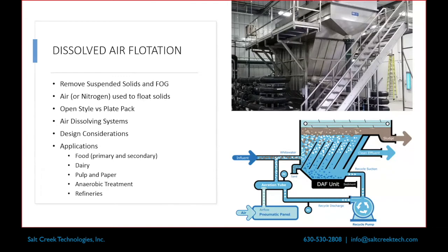So DAFs, like we've said, are good at removing suspended solids, really good for high FOG applications. You're using air to float, or nitrogen in some cases. On anaerobic digesters, for one, the liquid that you're trying to clarify a lot of times still has some residual methane in it, so a lot of times you'll use a nitrogen DAF instead.